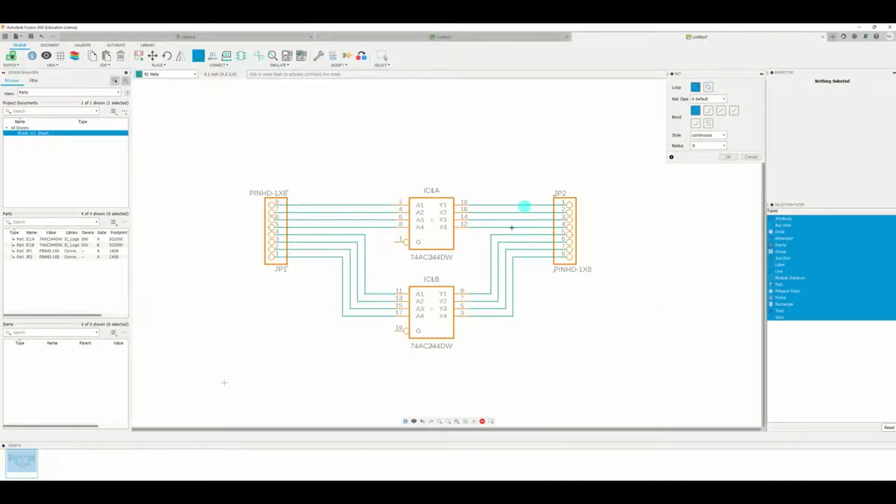input and our output. So the next thing to do now is have another signal here for the enable. Okay, so when you click or connect using the connector, do not move the line passing through the ends of your pins, otherwise they will be connected. So let's see, if you do that, let's say you wanted to do it like this and then like that, what will happen is they will be connected. Okay, so you can cancel, and of course you can undo.